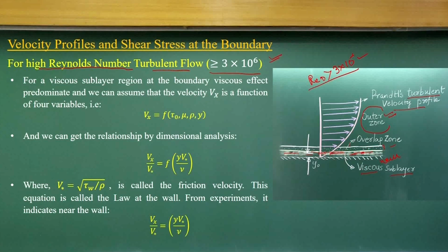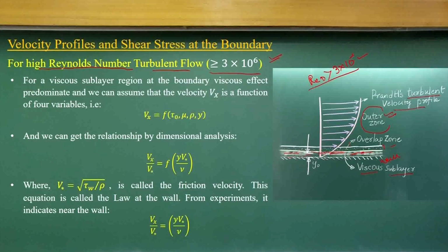In this lecture, we are not going into more details because I have not introduced the boundary layer concept, but try to understand it. When you go for higher Reynolds number flow, you will have a very small thickness near the wall where the flow behaves like a layer in which viscosity dominates, and that is the reason you have a viscous sublayer zone.